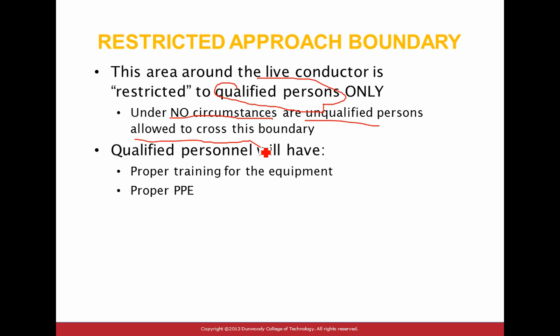That's the prohibited. Prohibited, restricted, and limited. Prohibited for the tool, restricted for the qualified person only, and limited for the qualified person only, but an unqualified person can come and give you a tool and leave immediately. When you are qualified and you are in the restricted, you have to have training for the equipment and the PPE. You enter the restricted, guys, you have to be suited up, put your suits on, and you have to be trained with the hazard that this equipment can initiate.